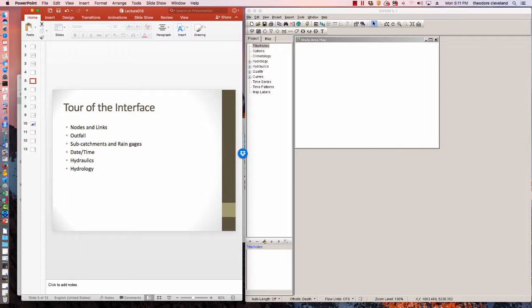They're also locations where the outlet from a subcatchment, or think of a small watershed, can drain to a node. And they have some other properties. There's flow dividers, there's orifice outlets, and so forth up here in the menu where you select whether you're going to have French fries or onion rings. There's one special type of node, which is the upside down triangle. It's an outfall node, and all SWMM models have to have one outfall node for them to run.